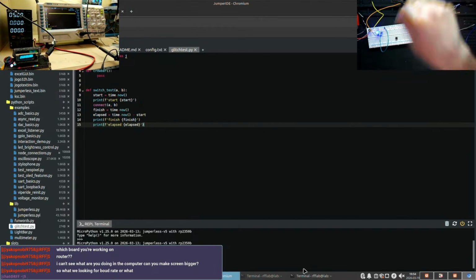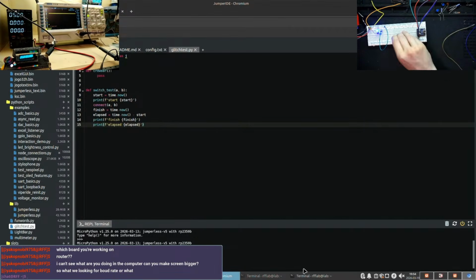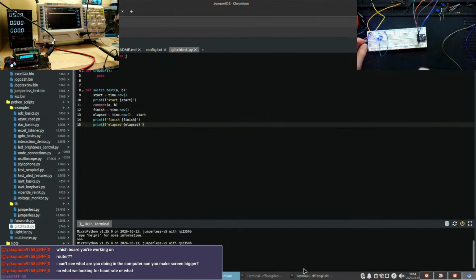Alright, so our maximum is at... We can even set up a button to sync this to ground if we want. Because this is also another mechanism that you can do for voltage glitching, is you can just use a simple button. You don't actually have to have a crazy complex circuit or a crazy setup. You can just use a little button and a wire that goes to ground, and you can drop the voltage on a trace and get it to do something fun.